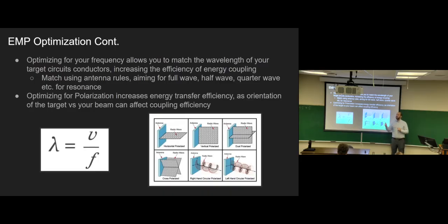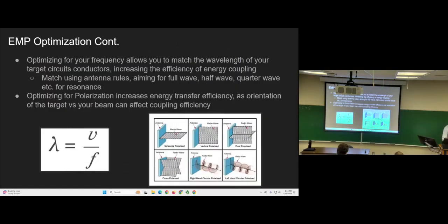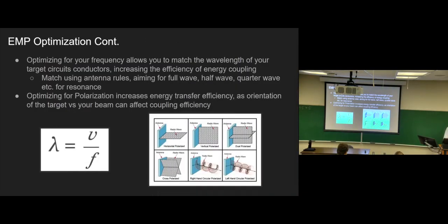So when you're talking circular polarization, it's a more complicated antenna geometry, so it's generally pricier. To get a really nice beam, a circular antenna is going to be a lot trickier than, let's say, a linear one. Because a linear one is simple, it's easy, it's like, oh, it's just straight. But the geometries of circularly polarized antennas, let me see if I can find one really quick. A common style is a spiral antenna. What on earth is this? There we go.